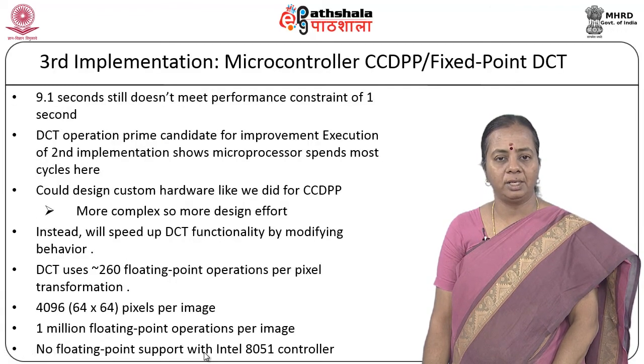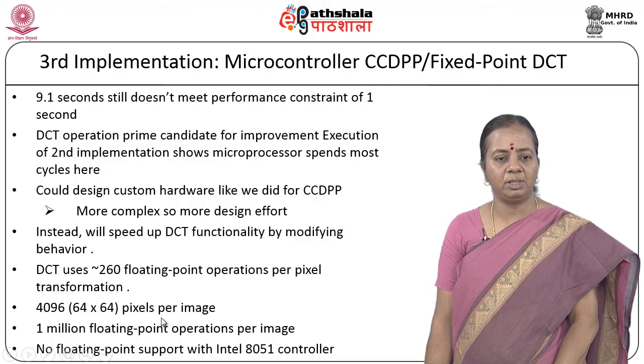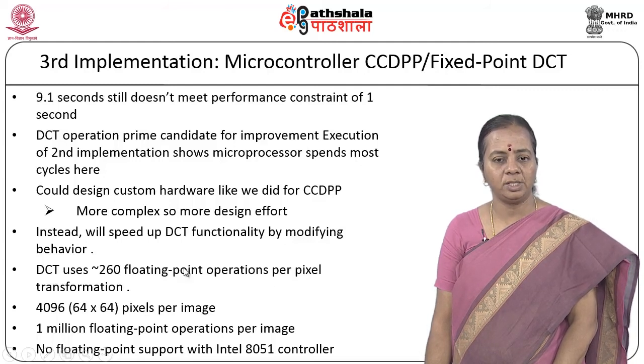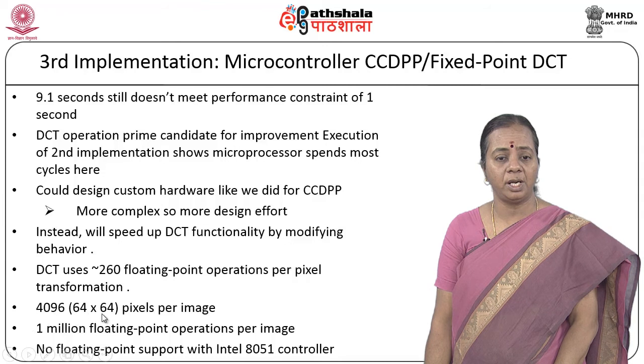So, when you are looking at the third implementation, it has the microcontroller, the CCDPP, as well as a fixed point DCT, because we made a fixed point processor for doing this DCT. It can be done very fast. The DCT requires 260 floating point operations per pixel transformation. So, remember that per pixel it requires this much operation. When you are looking at 64 cross 64 pixels, then 4096 operations per image DCT uses.